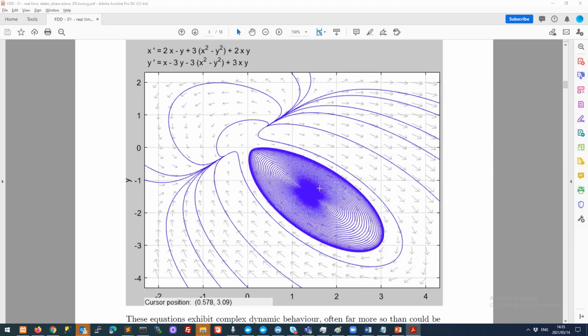So there are two attractor steady states and one repulsor steady state. And so out of all the places you can start, you will eventually end up on one of these two steady states, right? So that's the kind of hidden feature here. Originally it looked like anything could happen. We had no chance of designing a controller. But now if we look at our equations just slightly differently, we can find features, we can find little clues about how the system is actually eventually going to behave.